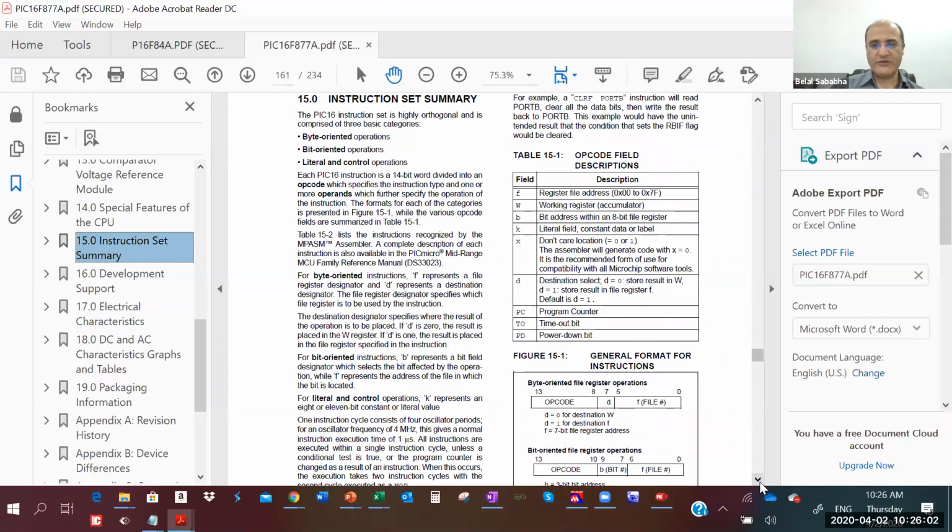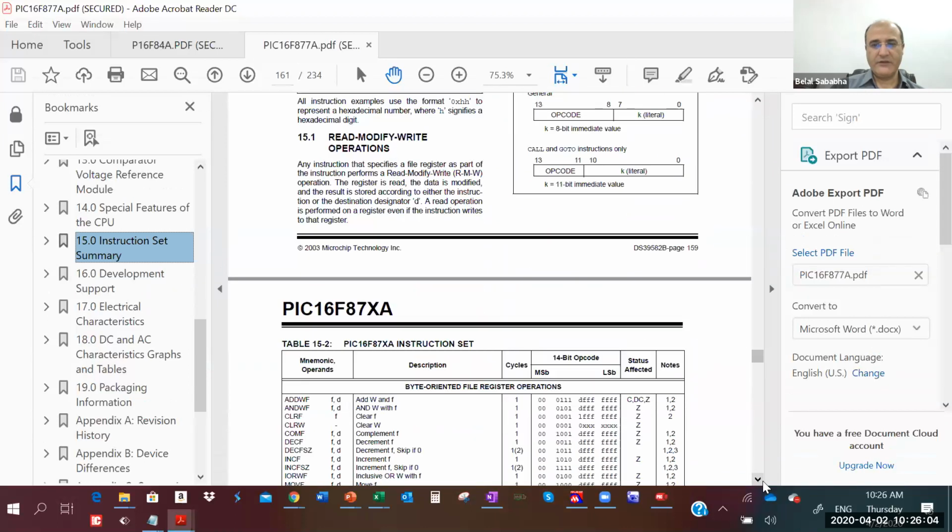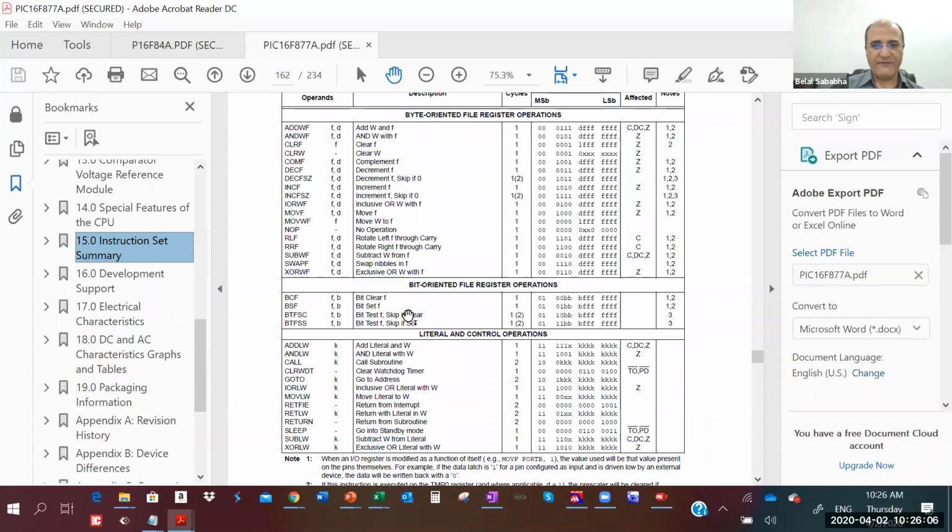So you go to the instruction set, and then okay, bit set F. It starts with 0101, then 3B, which is the bit number, in our case 101, a bit 5, right? And address 3 is 00000011. Convert it to hex, and you'll get that number.